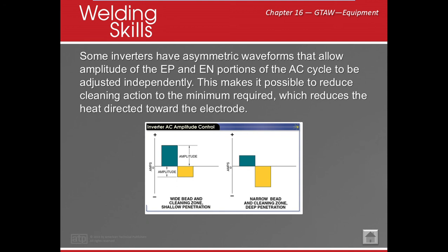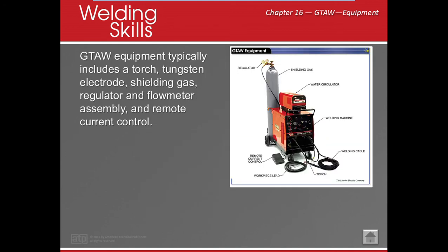All right. So let's talk about machines. We're going to need a machine. What's our machine? Okay. So of course we need a welding machine. We need to make sure it is capable of CC power. Nowadays machines have CC, CV, or some of them have both. Okay. If you have an air-cooled torch, you're not going to need a water circulator. But if you have a water-cooled torch, you're going to need an intercooler or a radiator.